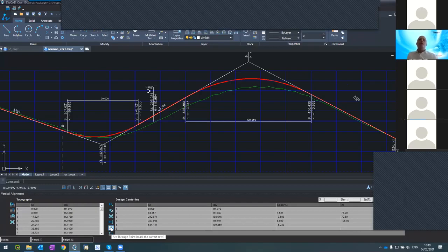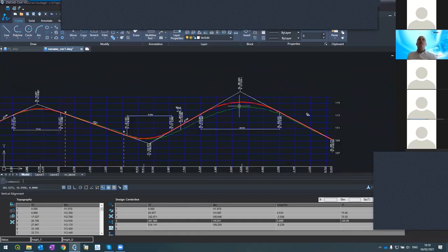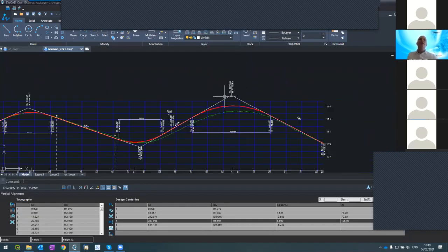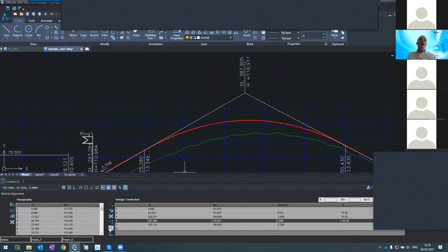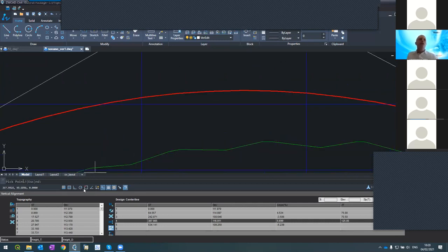First of all, I'm marking the curve itself. This is curve number 4, right? This is 387.9 meters from the start, which is this one, 387.9. We see it the same. Then I click the button and I tell the software where I want my curve to move through. Let me use object snap.